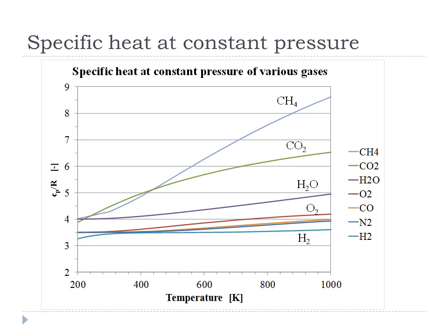Carbon dioxide, as a linear triatomic molecule, should have had a value of 3.5 R for its specific heat at constant pressure. But you can see it's already above that at 200 Kelvin. The reason is that it has a symmetric vibrational mode that is starting to become active at 200 Kelvin. And you can see the character shape of this curve.